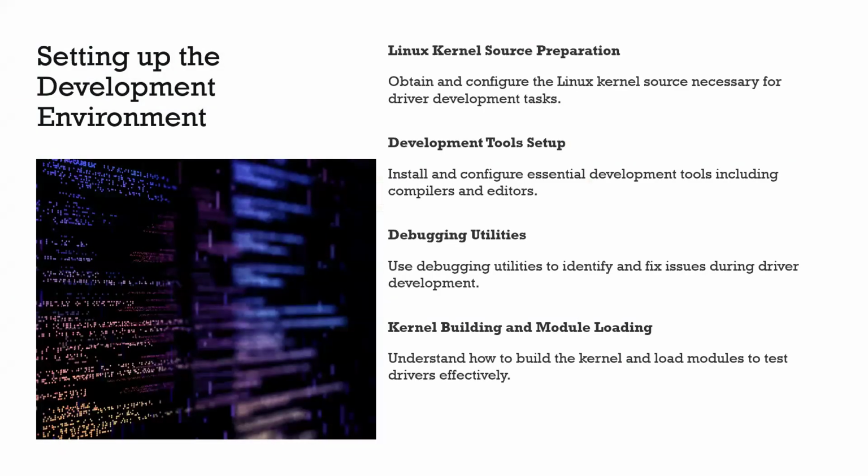Basically, you need to set up a Linux kernel environment. The easiest way I'd suggest, if you want to learn Linux device drivers, is to get a Raspberry Pi, maybe the latest version, which is the 5, and install the Bookworm OS.